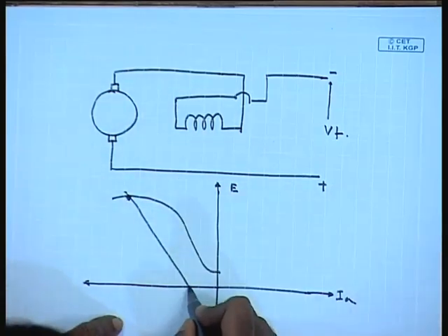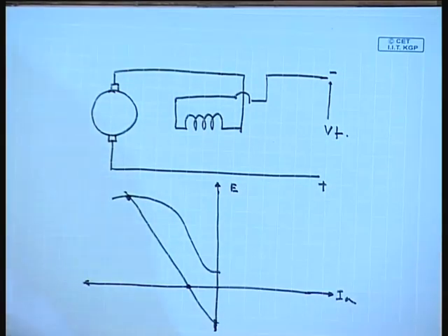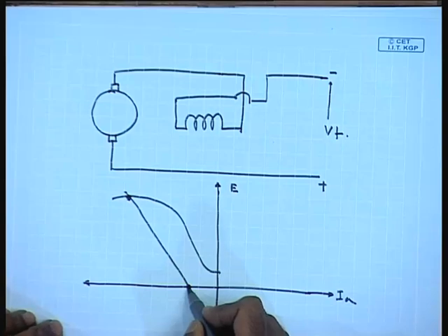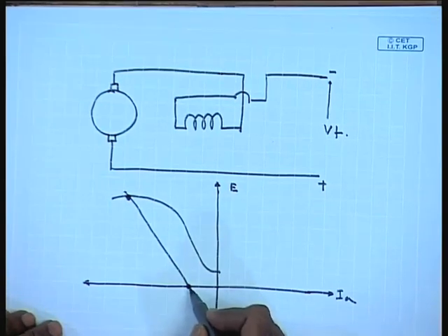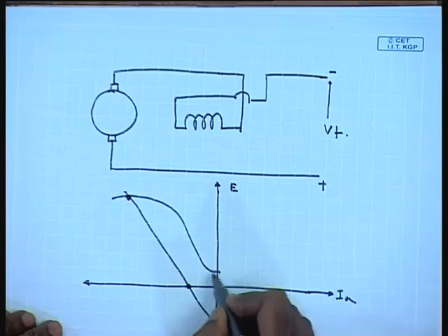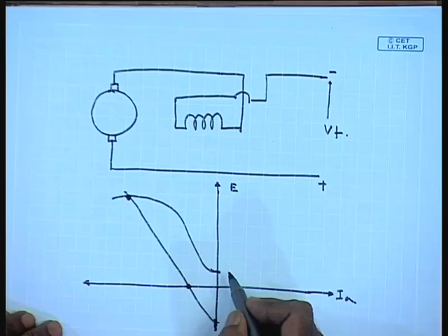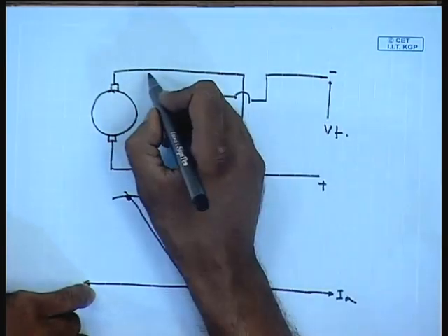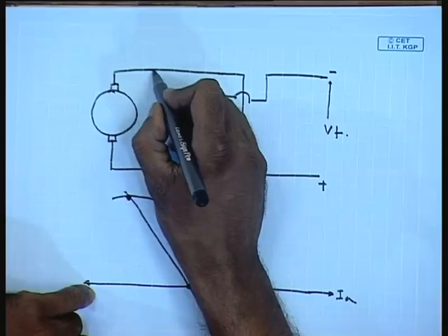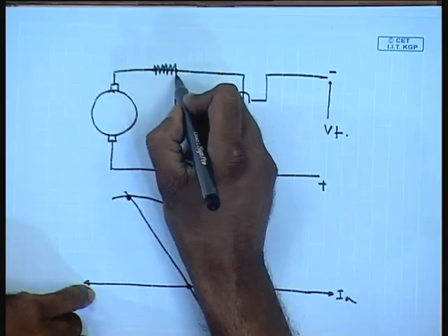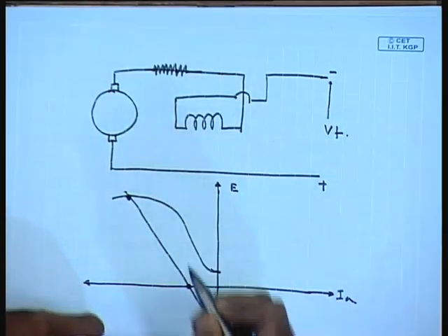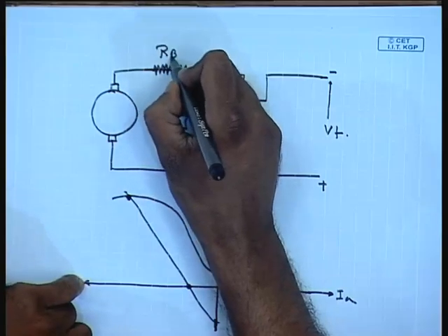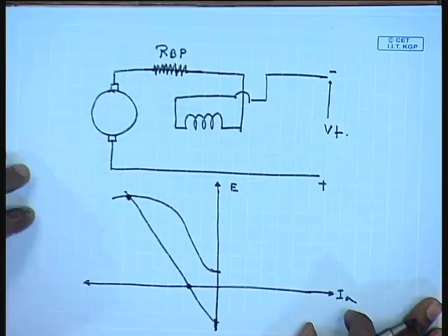We see that for plugging, the value of the braking torque at 0 speed is not 0. So, there is a possibility that the machine will start rotating in the opposite direction. Of course, the current can be very large, hence it will usually be necessary to put additional resistance in series with the armature while resorting to plugging.